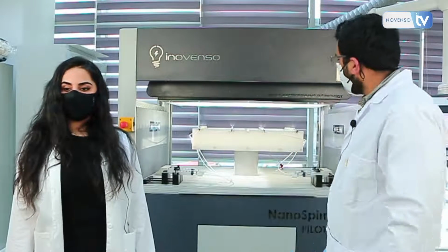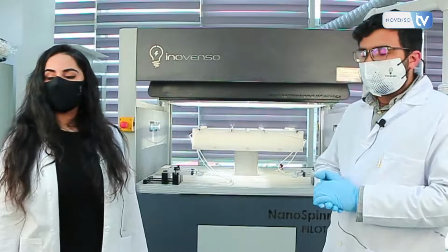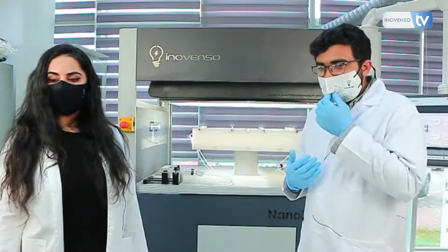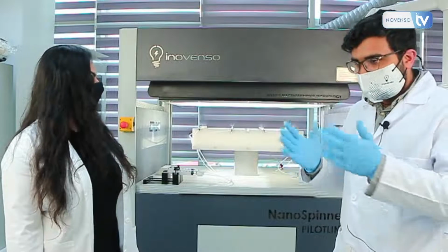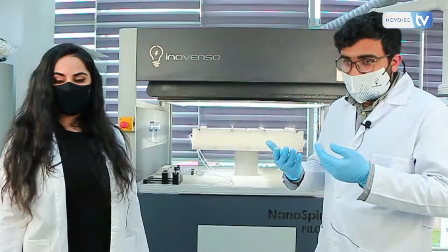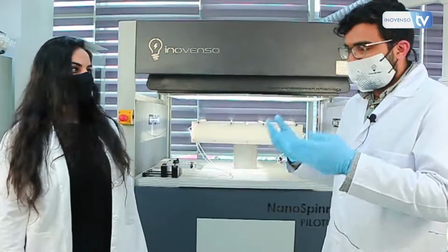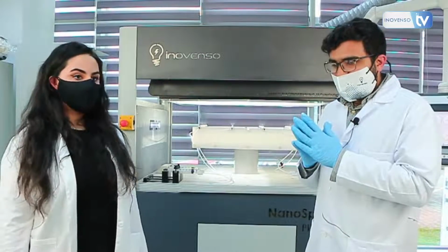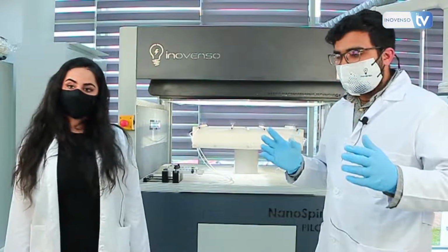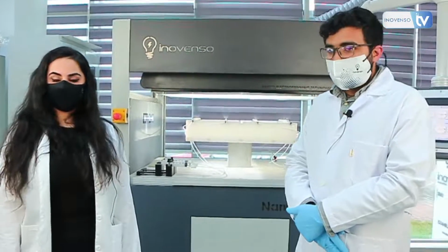So yeah, you can produce various polymers with this. The main challenge for you guys is to optimize the recipe, right? Optimization is key. Just like with lab scale electrospinning, you need a certain flow rate, a certain distance, and a certain high voltage, and of course solvents matter for viscosity. After several tests and experimental trials, if you properly find the optimized recipe that produces clean, good nanofiber meshes, you can always use that for the machine. That's the main challenge of the PE550, to work on a polymer and try to find the recipe. Once you have it, then it's smooth sailing from there.